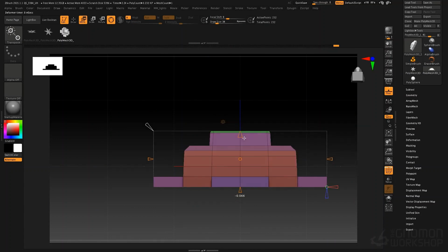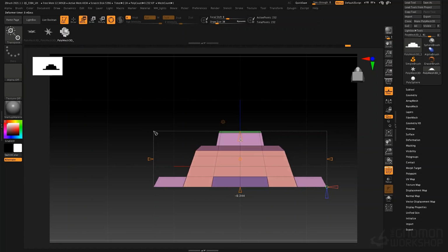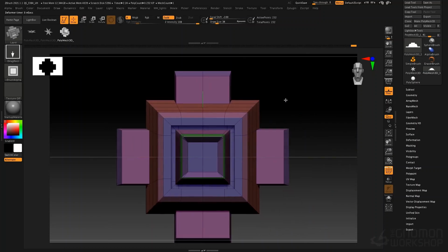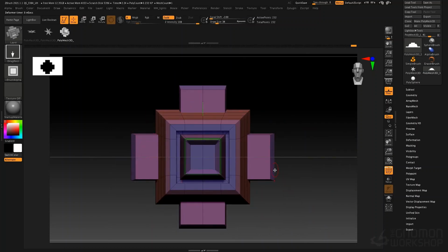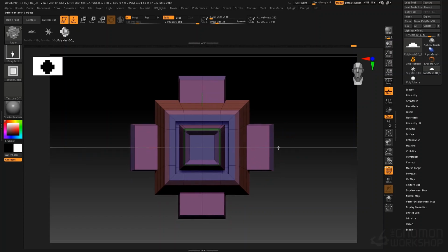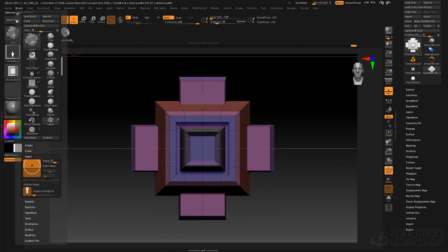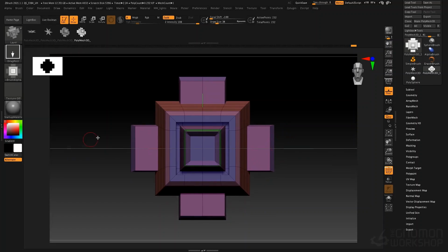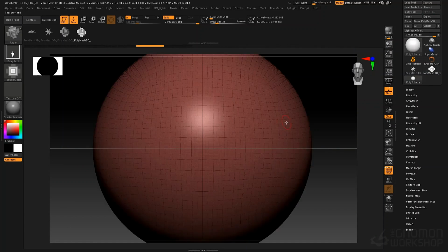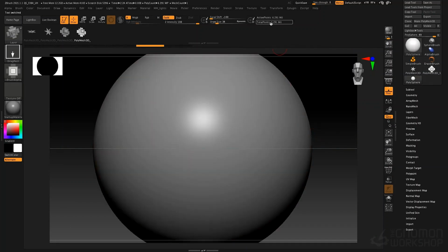And let's taper this brush along the top here, so it becomes more of sort of a trapezoid shape, like this. Now watch what happens if we store this one, where we've got an angle going back towards the base of these pieces. So I'll go to Brush, from Mesh, go back to our polysphere, turn off frame mode, and we're still at 6 million faces.